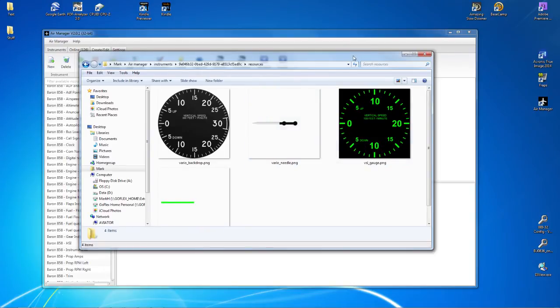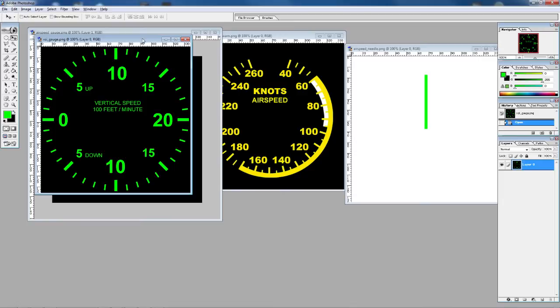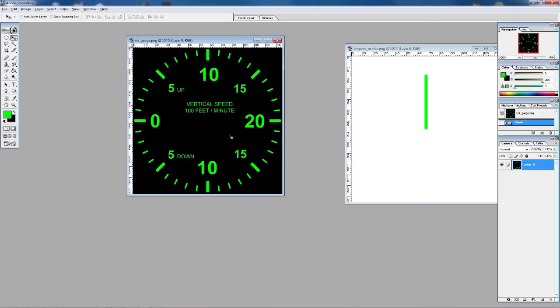So that's ready to go. Just talking about the range of values that I've made available to us. It's not the range that's available in the Twin Otter. The Twin Otter gauge goes up to 6,000 feet per minute. But actually the reason for this HUD is we're only going to need this in critical phases of flight, during the landing essentially. And if we're going anywhere near 6,000 feet per minute, up or down, when we're on the approach, we're doing something drastically wrong. So I've designed this gauge so that anything over 2,000 feet per minute is clipped, and that gives us a nice sensitive gauge that we can watch. It's a good size. We'll get a good sense of movement.